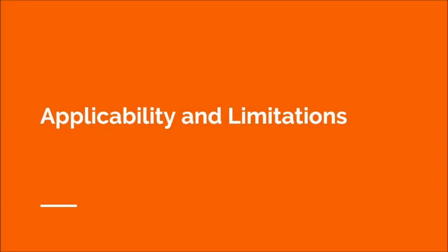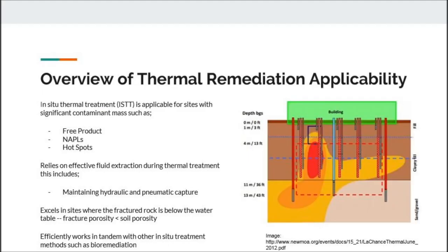So this section of our project is going to focus on the applicability and limitations of thermal remediation methods. So here's an overview of thermal remediation applicability. In situ thermal treatment is applicable for sites with significant contaminant mass. Effective fluid extraction is crucial during the thermal treatment process. This is done by maintaining both hydraulic and pneumatic capture within the treatment zone. Soil vapor extraction is the most common for fluid recovery.